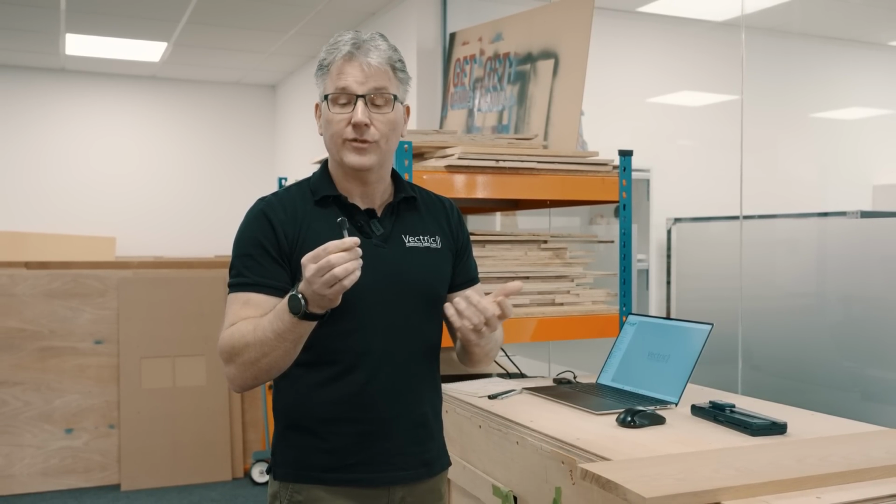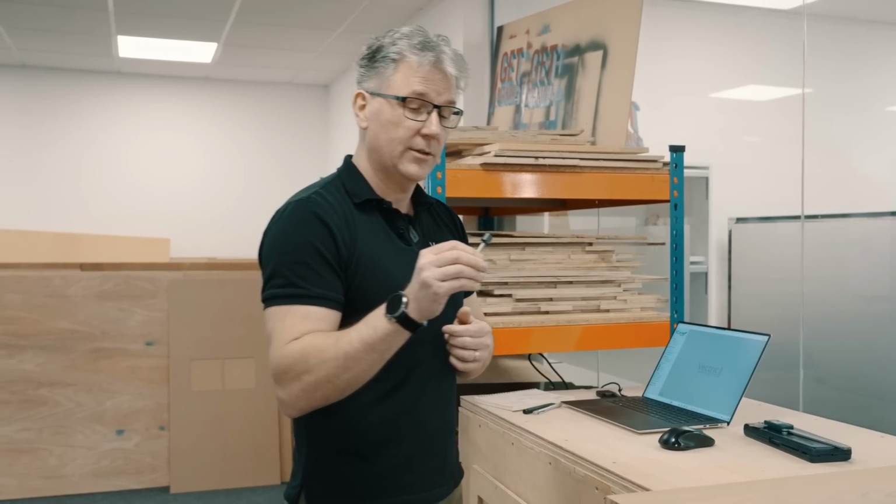I'm going to go through my tool database and find a tool that looks remotely like this. Find that, check the feeds and speeds, make sure everything looks relatively close, and I want to cut a test part. Now a test part I hate to waste, so I'm going to create a little tiny small olive dish, possibly, using the same sort of process to build the first bar stool that we're going to see. So let's go ahead into the software and I'll set that up and we'll cut that part right away.